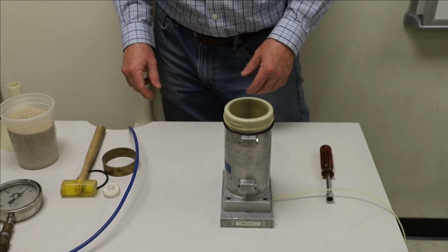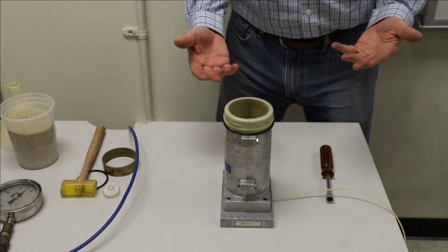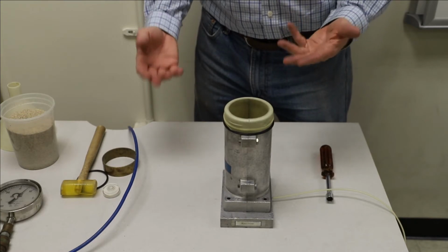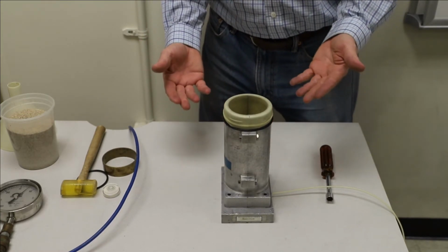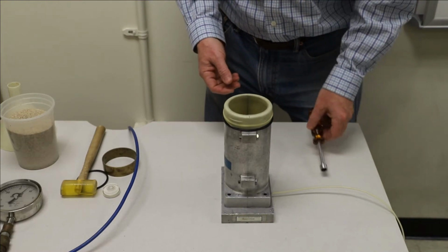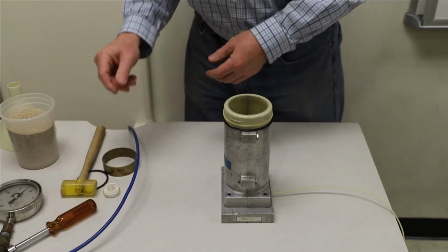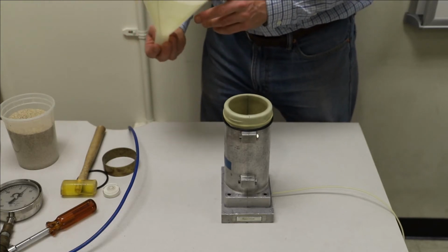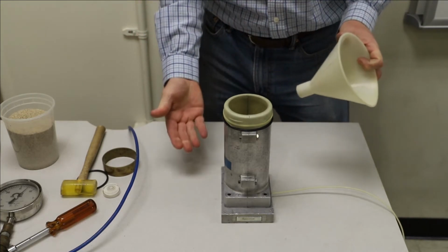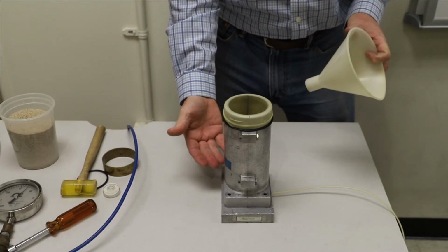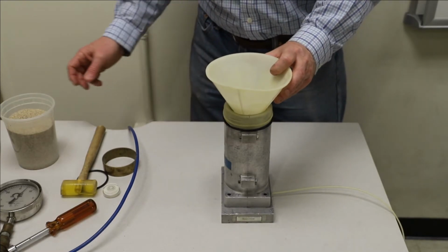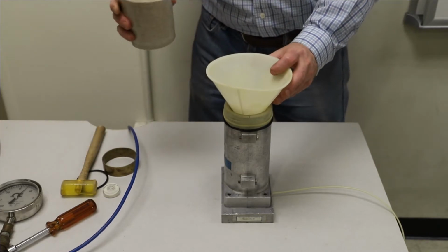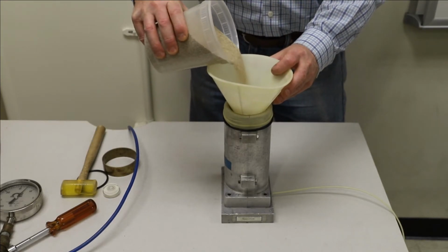inside of the mold. But now, instead of building a low density fragile sample, we want to build a specimen that's as dense as we can within reason. So we're not going to worry about vibrations, and in fact we're going to apply a lot of vibrations. So we're going to build this specimen in a series of layers or lifts, perhaps 5 or so, and we're going to just add some of the sand.